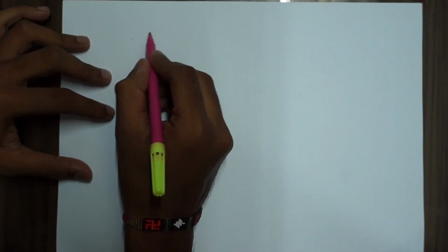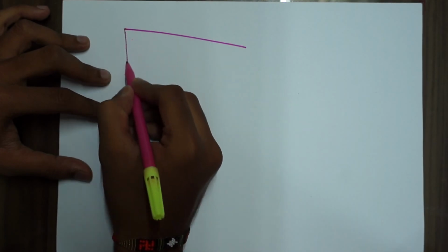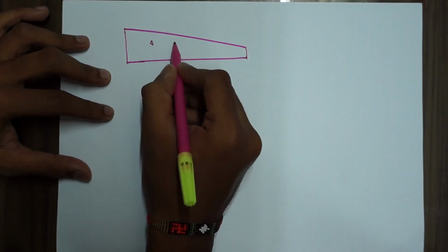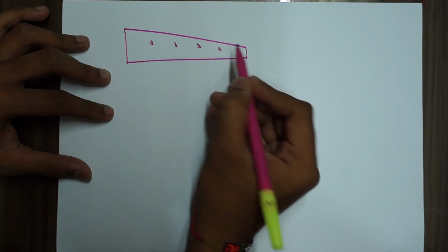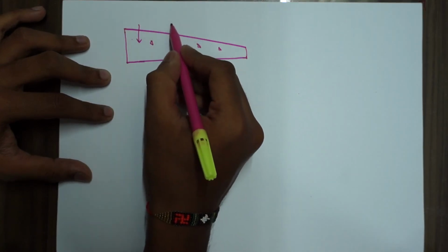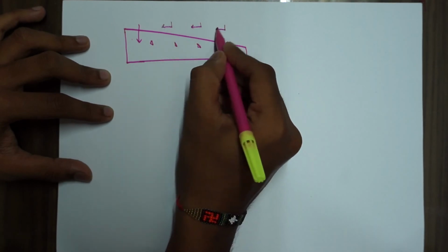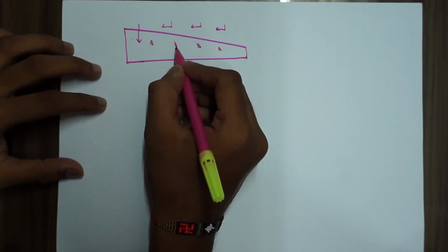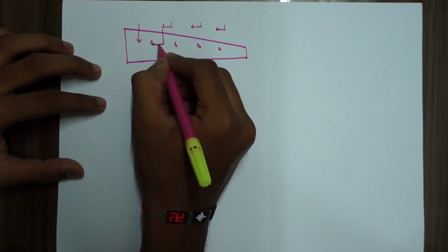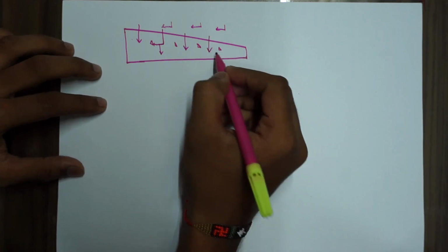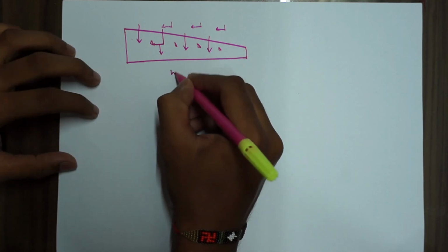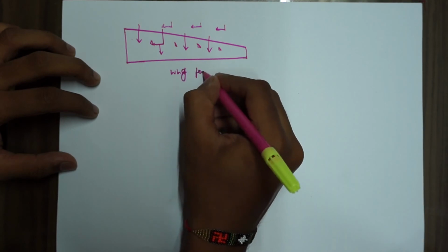Say this is the wing. Wing fences are triangular features on the upper surface of the wing. When airflow is flowing, it will flow straight through, and we have studied earlier that there's a movement towards the root on the upper surface. What these wing fences do is, when the air tries to move towards the root, they do not allow that, and the airflow continues straight forward. This avoids the trailing edge vortices basically. So wake turbulences reduce, and obviously the induced drag is reduced. This is your wing fences.